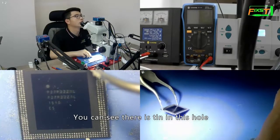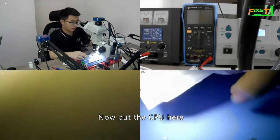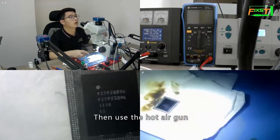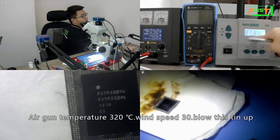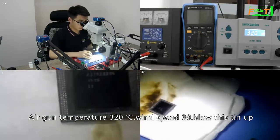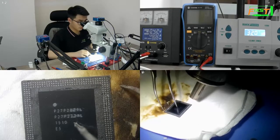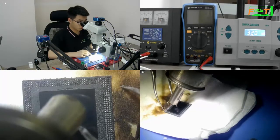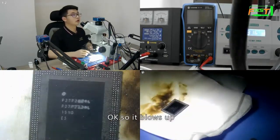You can see there is tin in this hole. Now put the CPU here. Then use the hot air gun. Air gun temperature 320, wind speed 30. Blow this tin up. Okay, so it's blown up.